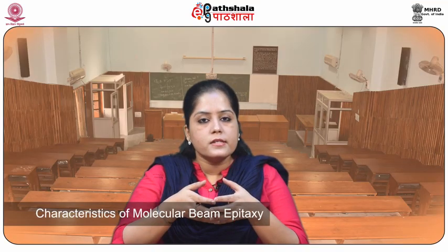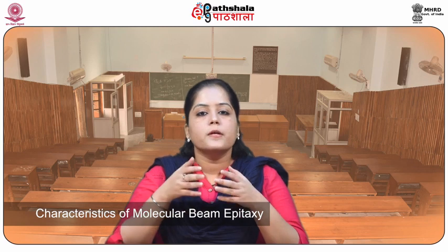So let us now discuss the characteristics of molecular beam epitaxy. Firstly, it has a low growth rate, around 1 monolayer, that is one lattice plane, per second. It has a lower growth temperature, around 550 degrees Celsius for gallium arsenide.